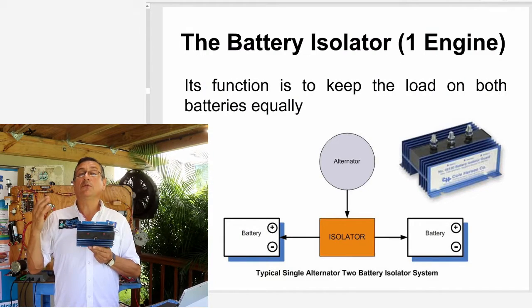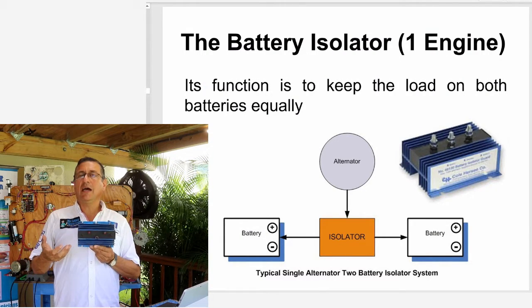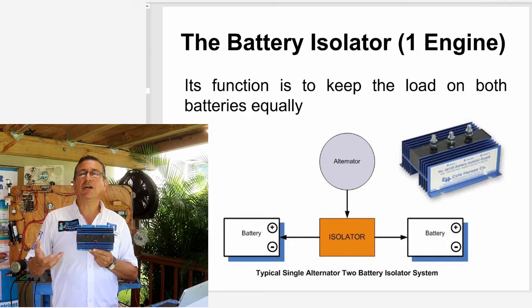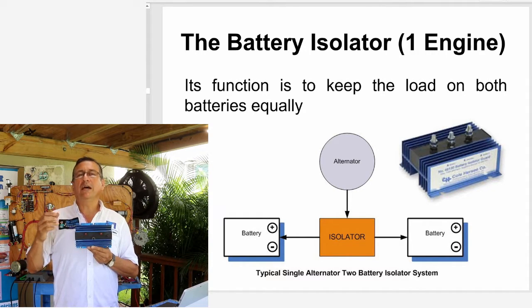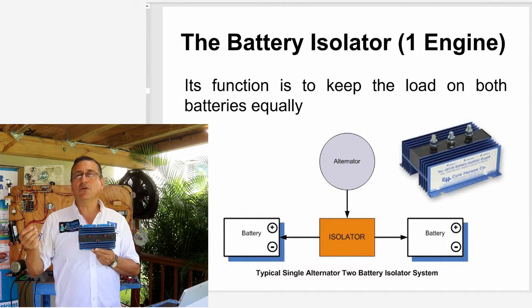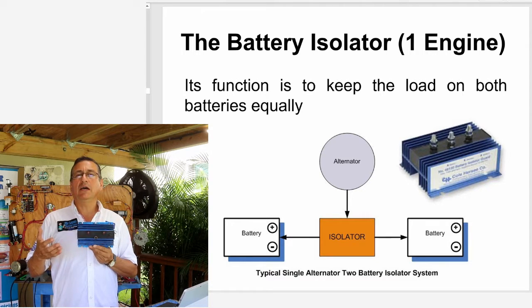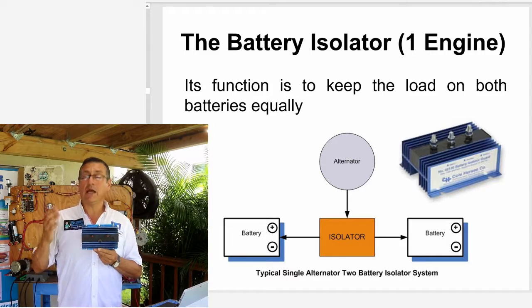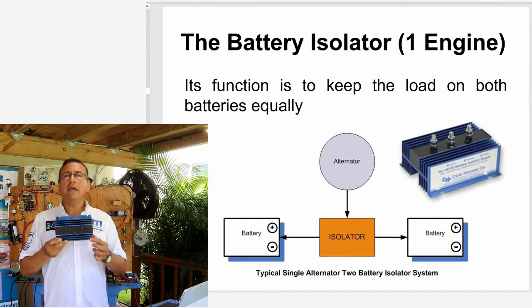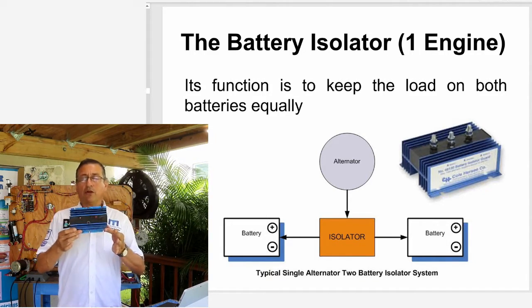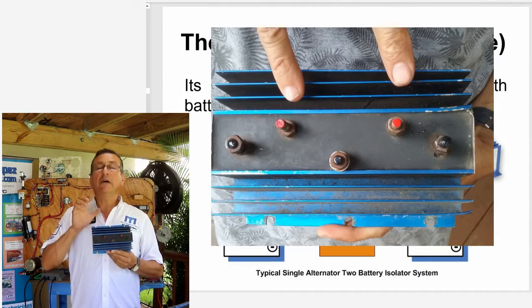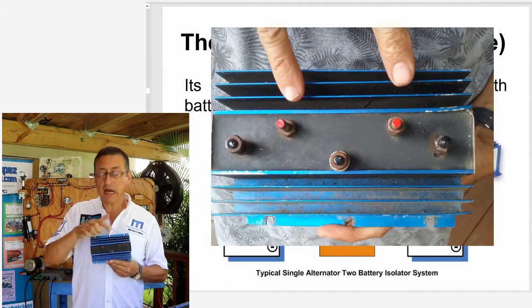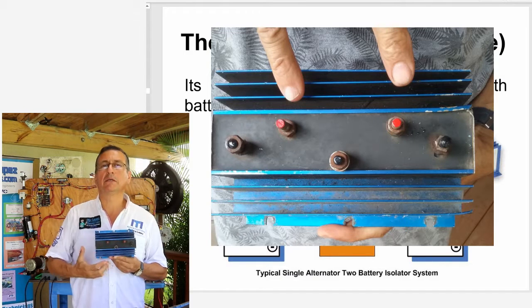Right now we are going to try to understand the meaning of 80 and how fast I can charge a battery with an alternator of 80 amps or 60 amps or 40 amps. What is better? In what situation is bigger capacity or less capacity recommended? Right now we are going to talk about that. Okay, but at this moment we are concentrated on the ACR. I have 2 alternators coming in and I have 3 battery banks.